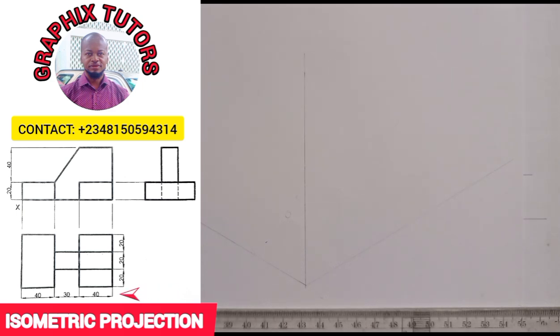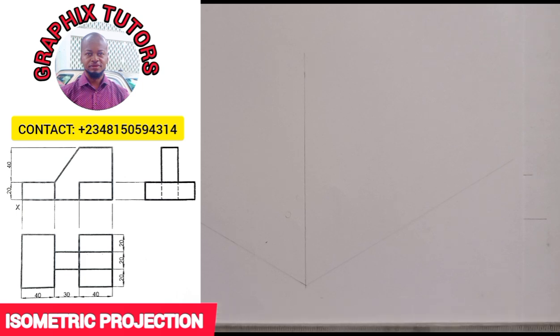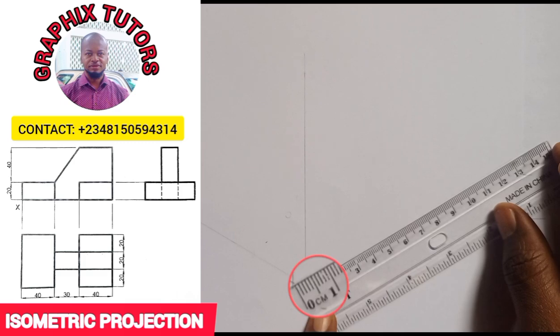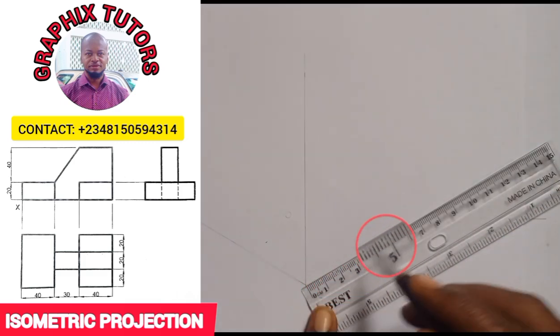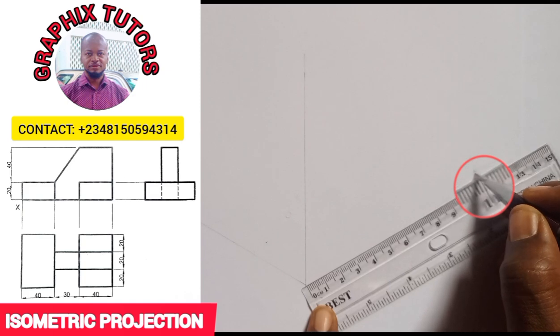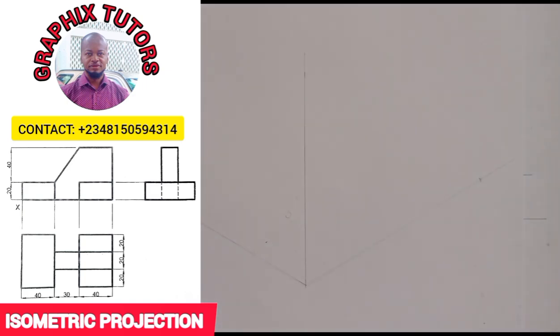So the elevation of the plan is given as 40, 30, 40. That is 110. So I'm going to take my instrument here and measure 110. You need to understand that this is from 0, then this is 100, and this is 110. Hope you can see that. Now, the plan is always below the elevation, while the one close to the elevation is the end view. So this is our plan, this is our front elevation, and this is our end view.